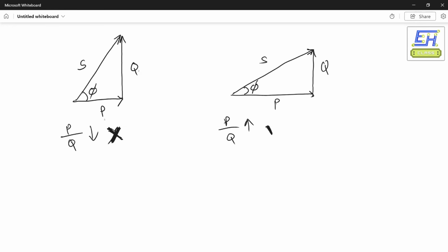So the other case will naturally be more suitable, because we are using more real power as compared to reactive power. This is what we generally see, and this is why we also correct the power factor in electrical circuits. This just means that we are using our power efficiently and not wasting our channel capacity on just the oscillations by the reactive components.